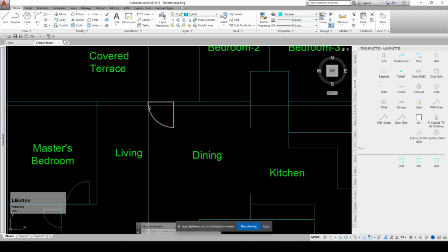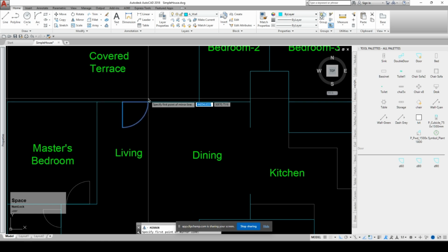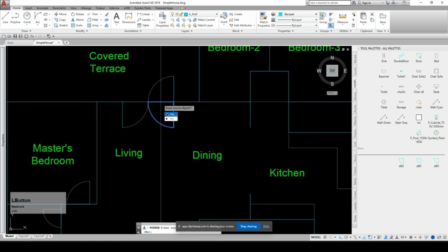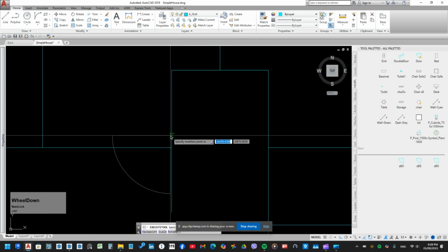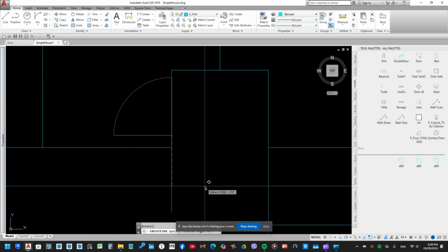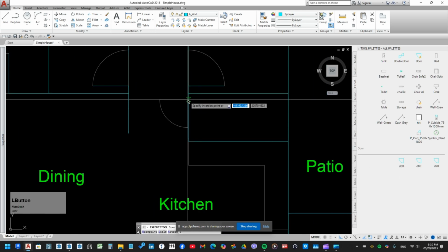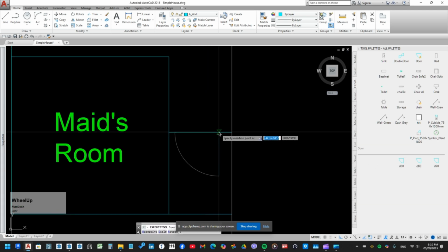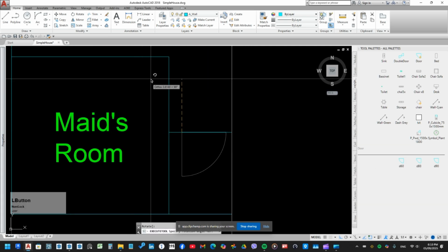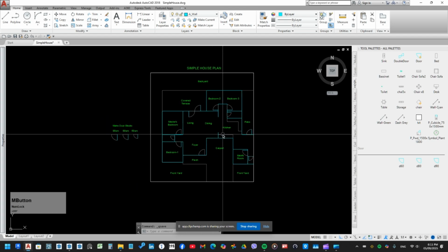Personally, I stick to 3 basic door sizes: 90 centimeters, 80 centimeters, and 60 centimeters for the toilet. This keeps things consistent and easy to manage across different projects. To speed up the process even more, I highly recommend adding dynamic properties to the doors, such as auto flip and rotation. These features allow for quicker adjustments and placement, making the workflow smoother and more efficient. Now save your CAD file, and we are now ready for SketchUp.